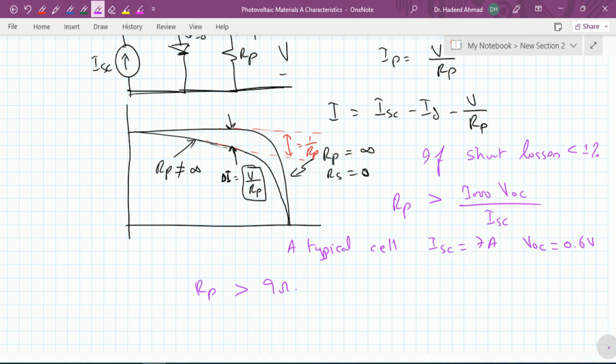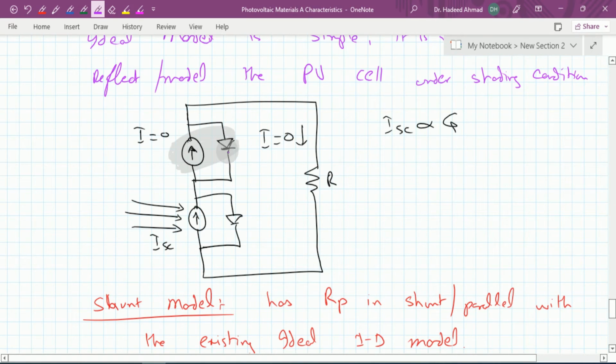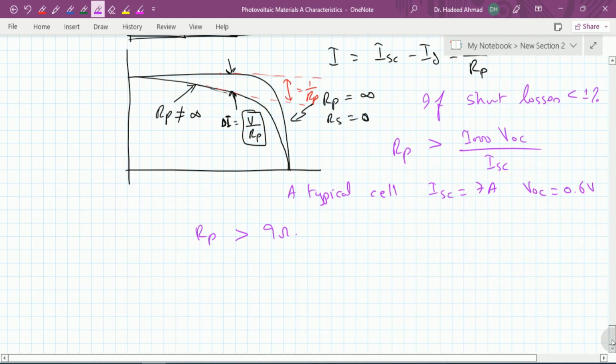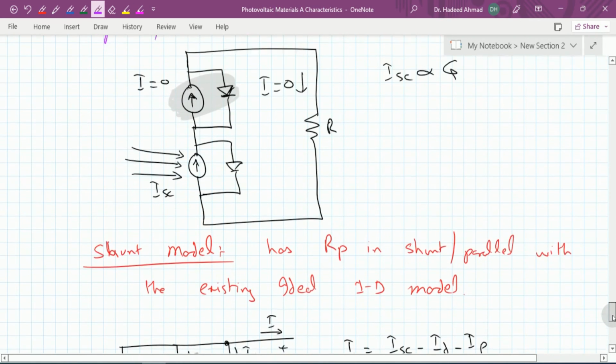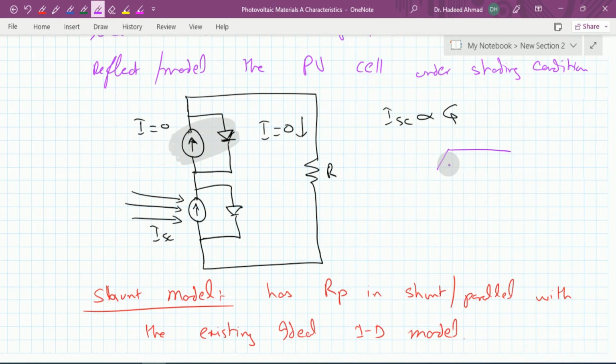Now this particular PV model can be used to see the impact of two cells connected in series. But before we move on to the impact of shading on a PV cell, let us introduce the losses encountered because of the contact resistance of the metal which collects the charges. On any given PV cell, we have these two conductors which collect the charges and are placed over the PV cell.